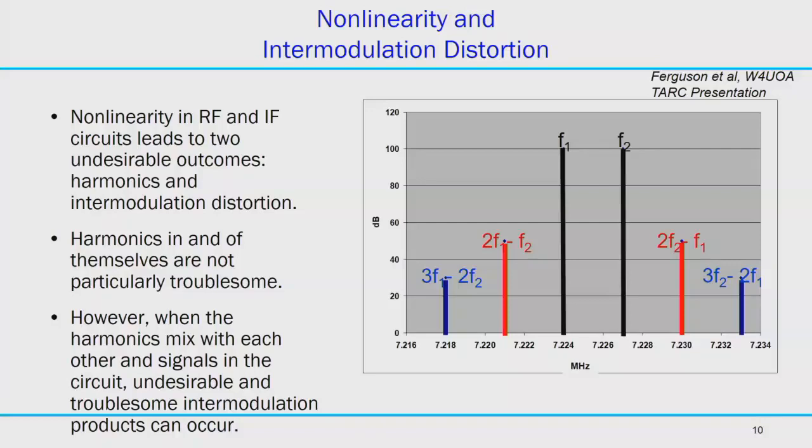All right? So those are the 2 reasons that you need to worry about nonlinearity and harmonics. These frequency components are called harmonics, and the distortion these signals introduce into your signal is called intermodulation distortion. Intermodulation means those modulation frequencies are mixing together to give you a signal at roughly the same frequency as your frequency of interest, and therefore it is called distortion on top of your wanted signal.